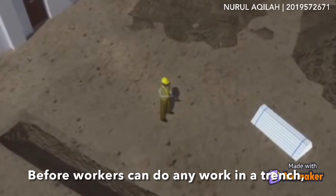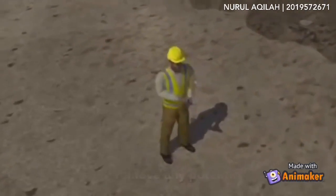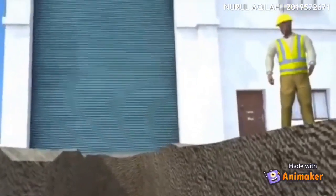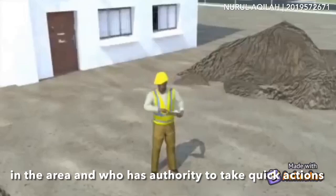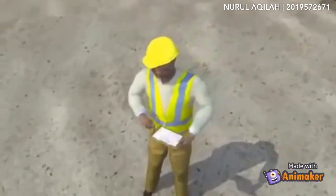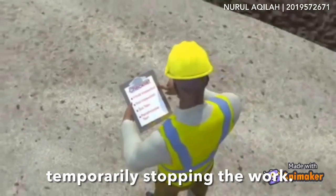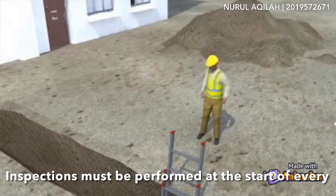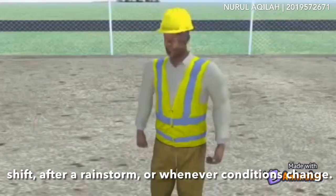Before workers can do any work in a trench, a competent person must conduct an inspection to identify and remove any potential hazard. A competent person is someone who can recognize hazards in the area and who has authority to take action to eliminate them, which may include temporarily stopping the work. Inspection must be performed at the start of every shift, after a rainstorm, or after a change in conditions.